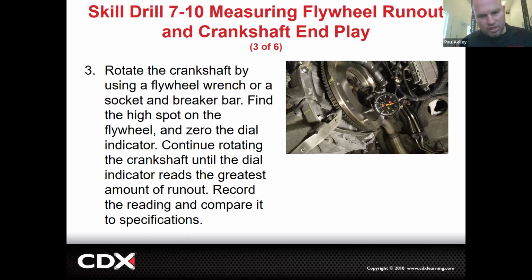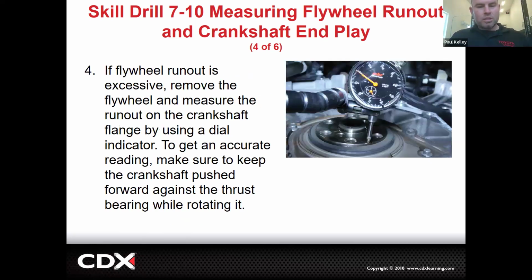See this? So this one is turning. This, by the way, is a special service tool to grab the teeth and turn a flywheel. That's a flywheel turning device. So that's runout. This one, it would probably be even better to not put it on the flywheel. It'd be better to put it right on the crankshaft. You could do two things right here. One, you could turn it.